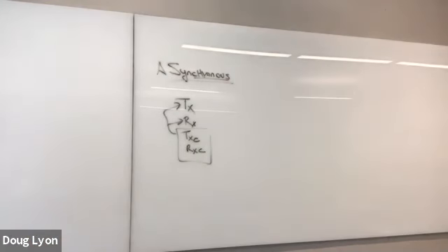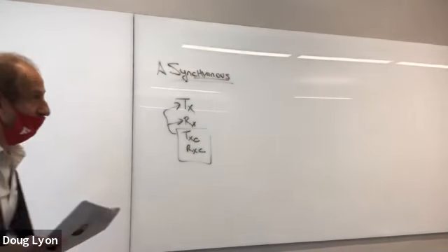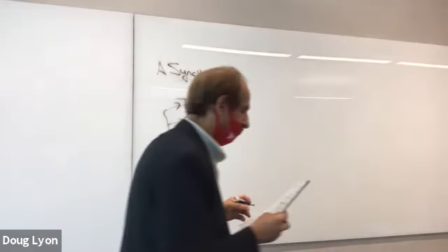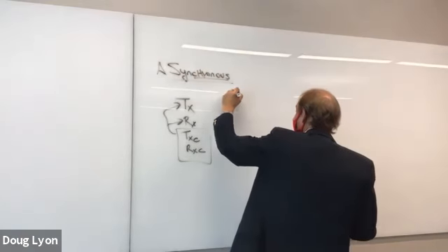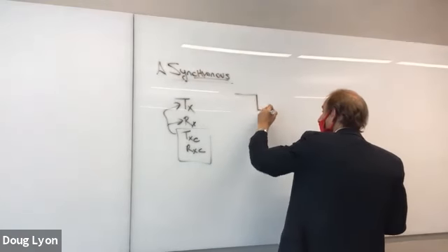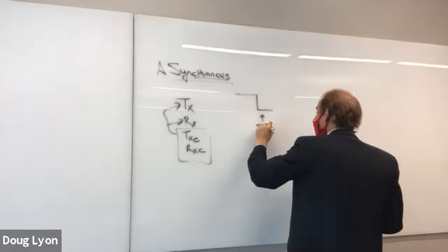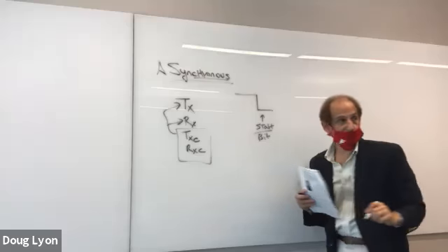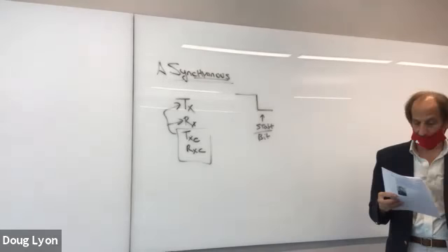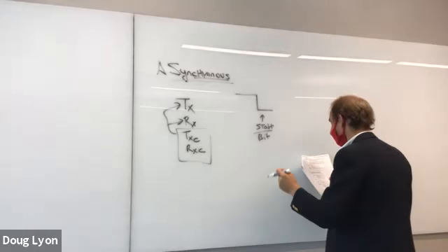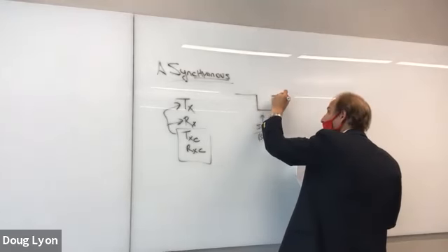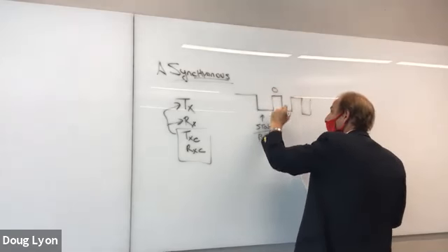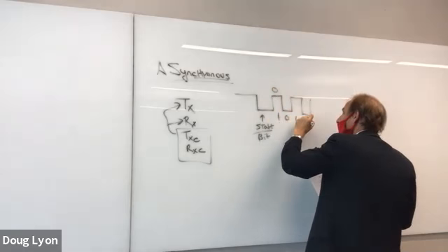So these transmit and receive signals are often distinguished from the data that you want to transmit. So you have a kind of overhead. We'll call this the start bit. This is what's known as a framing bit because it allows you to determine when the signal is going to begin. Then you have a series of pulses. It could be 0, 1, 0, 1, 0.